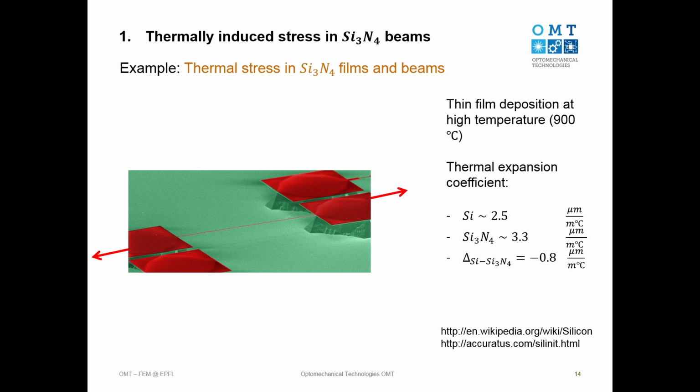Is that clear for everybody? So when they're moving away, they're pulling this beam with them. And obviously the substrate is 500 micron, and this thin film is 100 nanometer, so this substrate has much more power than this guy. Obviously, this thin film tries to resist this motion, but it cannot, because the masses are basically orders of magnitude different. So these guys win and actually really pull this.